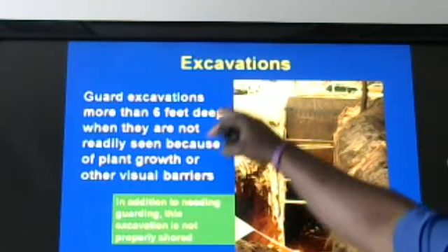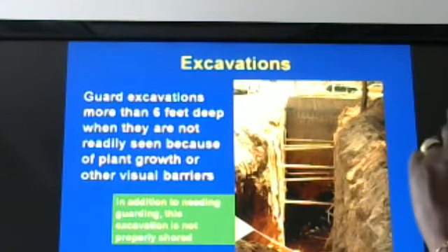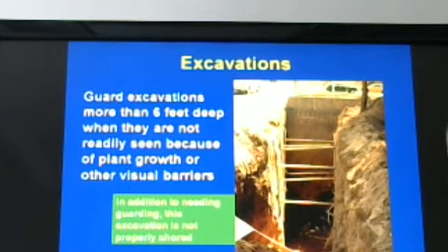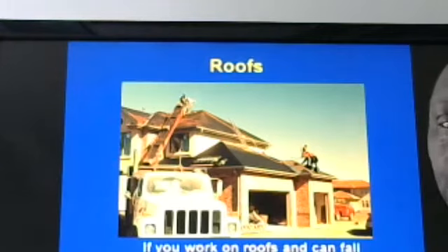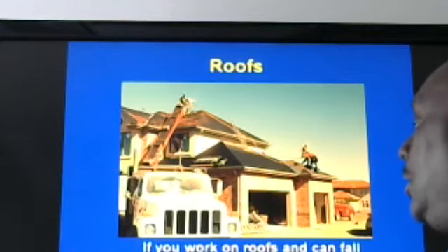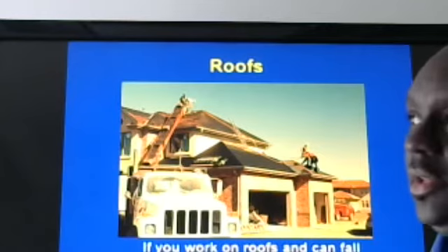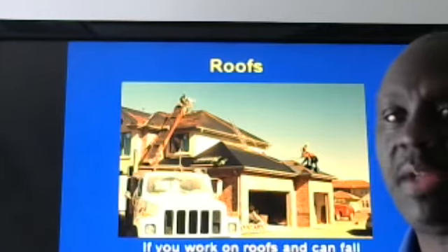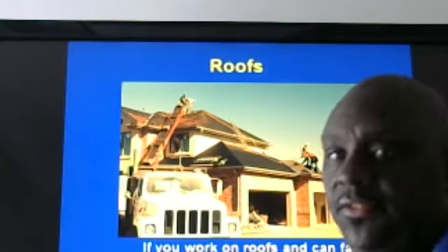Excavation, you see this one here, absolutely terrible. It's basically out to the public. You've got cars parking there. Kids come over out of curiosity. There's no protection in the trench, none at all, and this is where falls can take place. In roofing, it doesn't make a difference what type of work you're doing. They're talking roofing here, but for any type of work you do, you need to be protected at 6 feet.